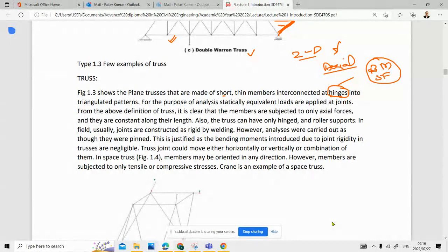Those are blunders which you are doing with the truss members, because those are hinges, and if the members are hinged, they won't be able to carry any moment at the ends. So there will be no end moments. There will be only axial forces on that hinge, either vertical force or horizontal force, right? Those things you should keep in your mind while doing the analysis of a truss member. And they are in a triangular pattern.